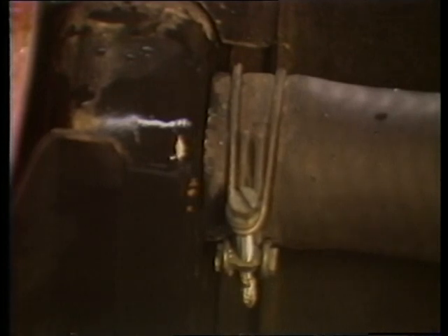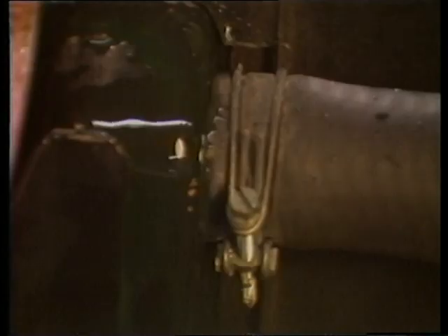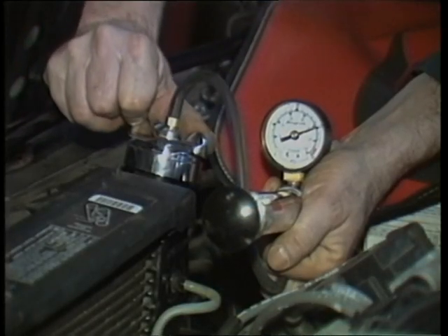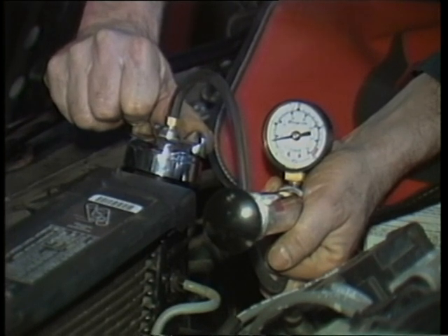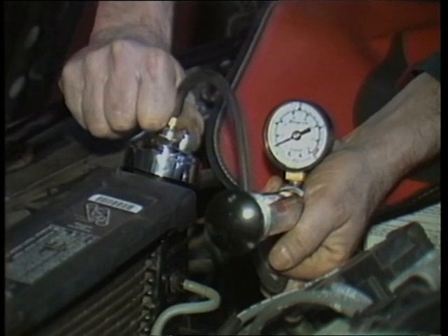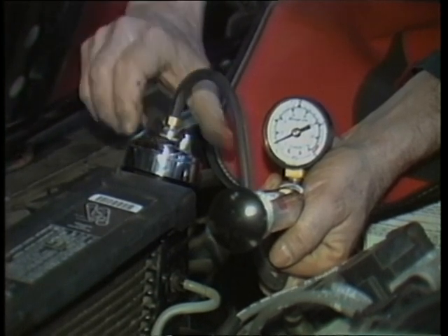Your repair may simply involve tightening a loose hose clamp, or it may involve time-consuming engine removal to get at hidden freeze plugs that have rusted through. Bleed pressure by twisting on the lever on the top of the tester cap. This will keep coolant from blowing out into the shop area.